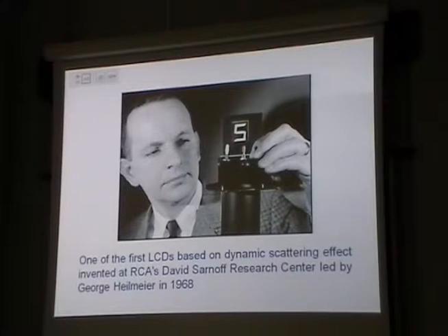And as was pointed out yesterday by Tim, scattering is one of the very first successful display demonstrations. It was dynamic scattering from RCA. We saw this chap in different pictures yesterday, with his actual display. However, it does link to this EHD effect, therefore it requires ions and currents to drive it, and therefore is not a terribly efficient or easy display technology to manufacture in large numbers cheaply.